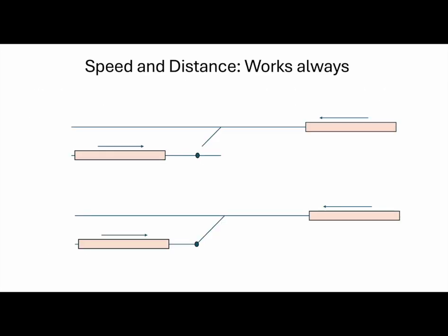So what does it mean, for example, in terms of flank protection, when we say the criteria speed shall match distance or distance shall match speed? How does that work? When you have a situation with two trains here at the top in a train-centric safety check situation, every time somebody wants to prolong his MA or wants to start a movement, the things reachable on his path are checked. So what distance do they have? For example, if the point is open here and this train is moving in that direction, for example entering a station, he cannot reach the other train, so there's no distance risk to be checked.